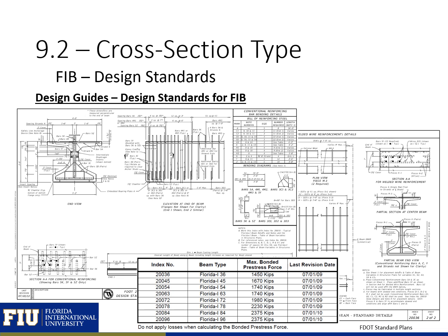Many states also have standard plans for their standardized sections. Shown here are some sample standard plans for the Florida I-beam sections. You can see they have standard spacing and location for all the transverse reinforcement, the spalling reinforcement, and confining or bursting reinforcement at the end region and then along the length of the section. These standard details satisfy most normal designs.